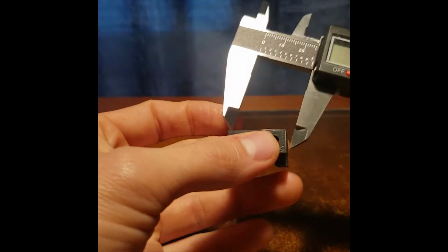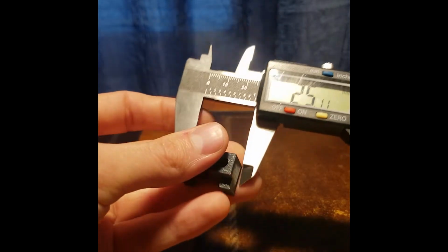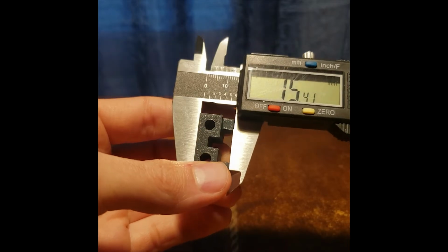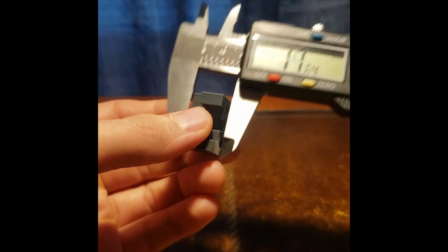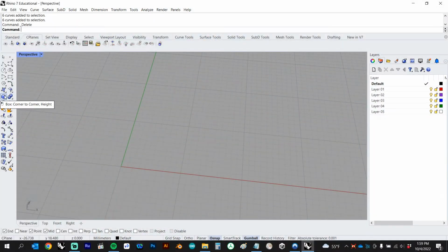For the subtractive modeling approach, we want to think about creating a solid that we can then remove pieces from to get our desired geometry. So I'm going to start out by measuring the outside dimensions of my object, which we'll use to create that initial solid, which we can call a primitive. In Rhino, we're going to use the box command and the dimensions that we just measured to create our primitive shape that we will then subtract pieces away from.